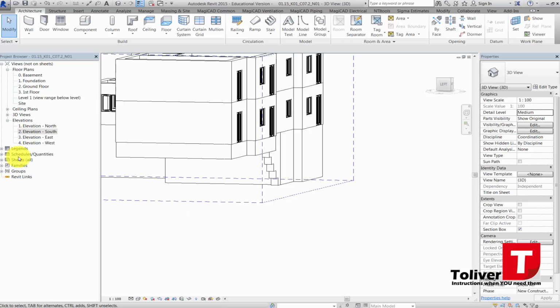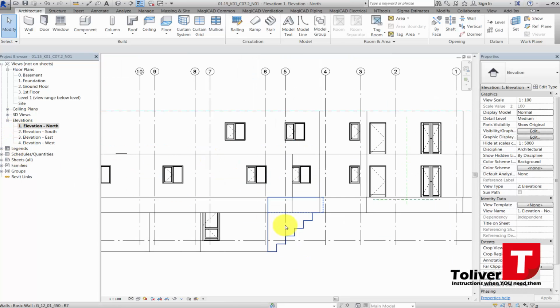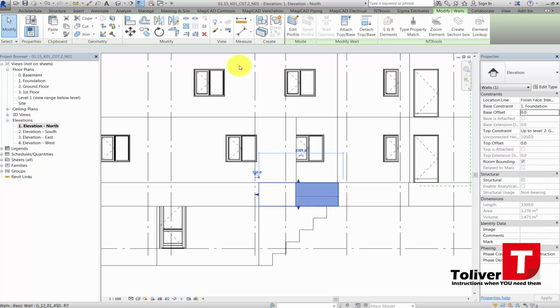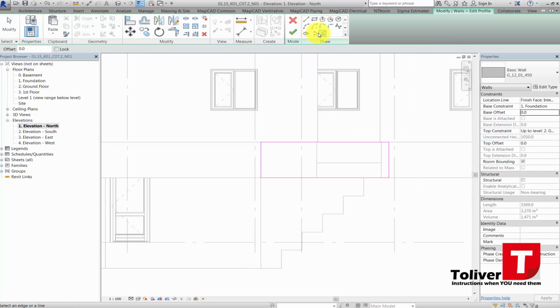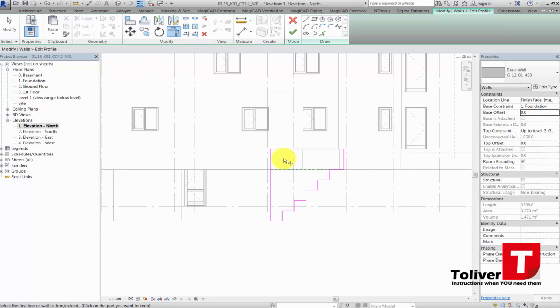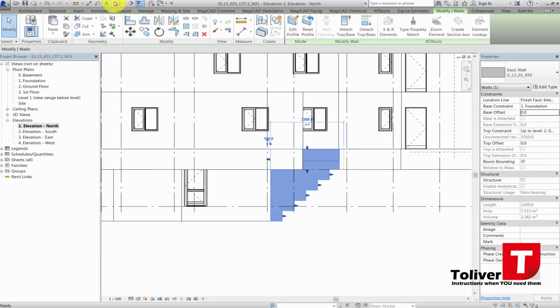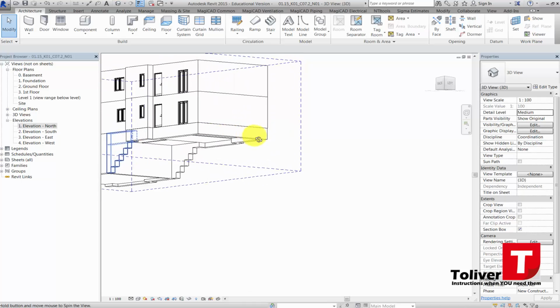I'm going to be doing the same on the north side. I'm going to pick this wall here, edit my profile. Now I know it's 532, so I can just use this one, pick lines. I can pick the lines like this because we already did one on the opposite side, and then trim or the TR like this, do this, and once you have that, you can take finish edit mode. Again, if I look at it, I actually have it on both sides now.